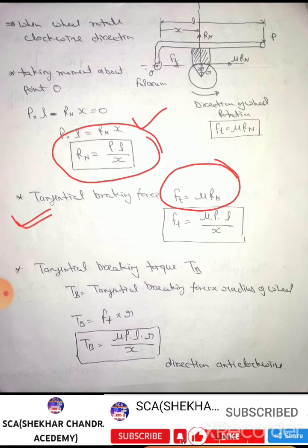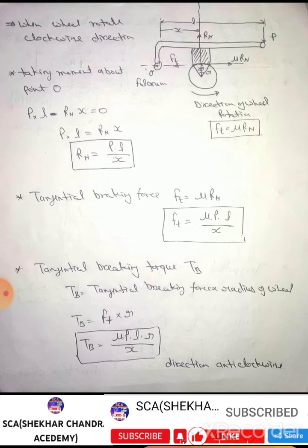The value of Rn is put into the tangential braking force. Now we obtain the value of tangential braking force as mu into P into L upon x.